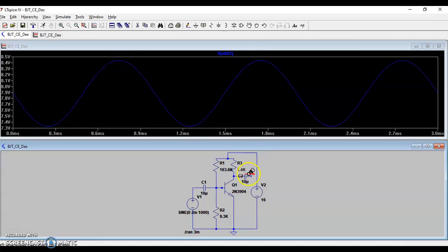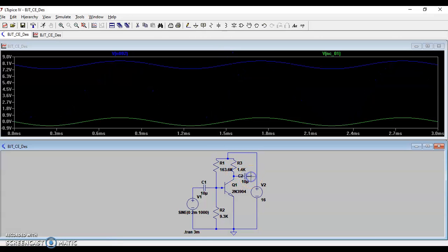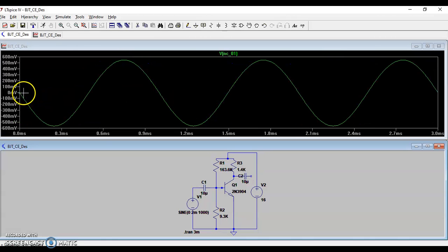Because at the output you want only AC output, when you take the output from after this capacitor, your DC will not be available here. So your AC fluctuates about zero. So you can see AC is fluctuating about zero. So you only have the AC collector to emitter voltage here, right? So this is your output. You can see 5.98, what is the value? It's 5.44, right? It's just because of some mismatch between the parameters of this transistor and the one we have taken, right? So it's working perfectly.